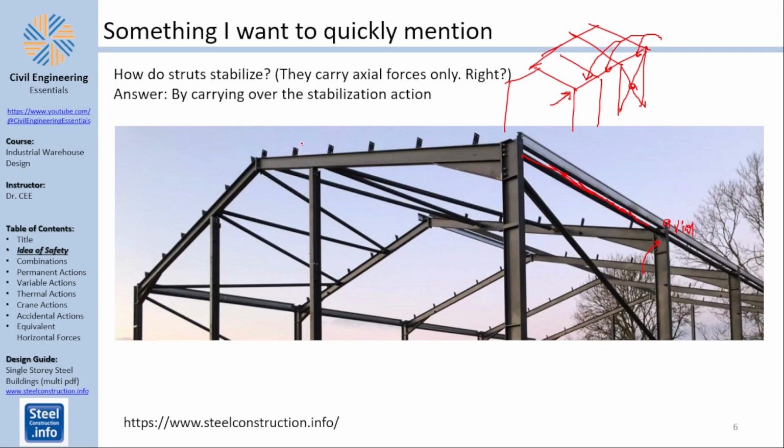You can also see those cool details about the purlin connection. I cannot see any stabilization of the bottom flange here, maybe because they have not yet provided the cladding. I don't see a connection even here, so maybe I'm wrong, I don't know. Notice that there is a stiffener here because the compression of the haunch will impact the column, which gives you a stiffener. It seems for this portal frame there was no need for a haunch at the apex. Maybe the distance was not that much.